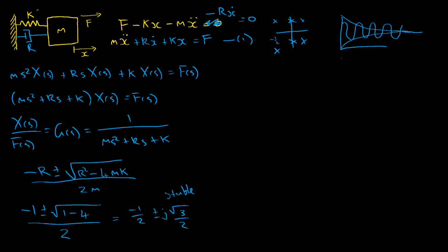And so that's the introduction to second order systems. In particular, the things that are important here is if we have a complex component to the eigenvalues or the poles of that system, we're going to get oscillatory behavior. If those poles have no real component, our system will be marginally stable. If they have a positive real component, it will be unstable. If they all have a negative real component, it will be stable. If we were to get rid of the oscillatory behavior, so the imaginary component, you'd see we'd actually get our poles on the real axis and we'd be back to just summing first order responses.